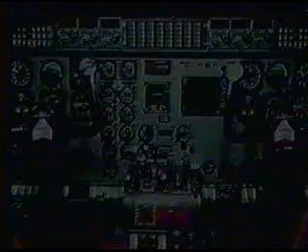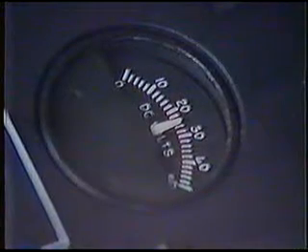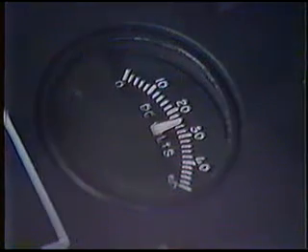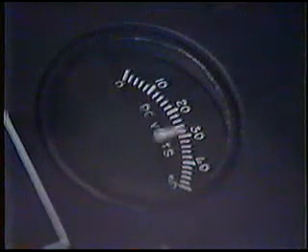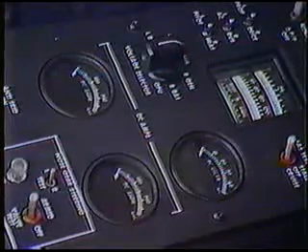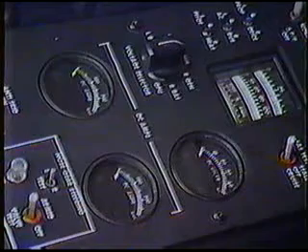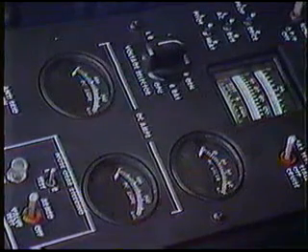Because of the DC generation system's importance to the aircraft's safe operation, the condition of this system is carefully monitored. Primary cockpit indications include the voltmeter circuit, which allows the pilot to determine the voltage at each generator. In order for the reading to be accurate, the generator switch must be in the off position, so that the generator is not connected to the aircraft wiring and supplying a load.